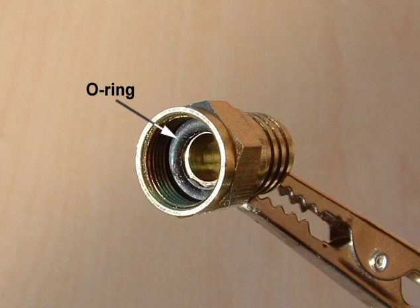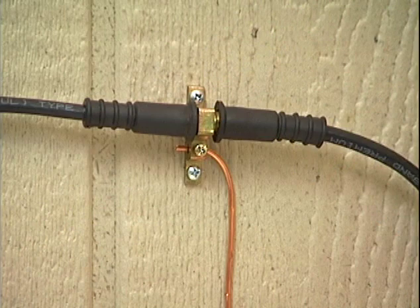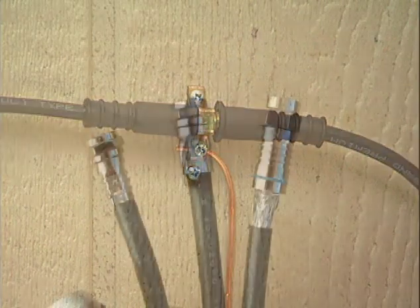They have a built-in O-ring seal, and the crimp barrel has a dielectric silicon compound pre-applied to keep the moisture out of the coax. We also recommend using a weather boot. This keeps moisture and UV off the entire connection. You just have to remember to put it on the coax before you apply the connector.